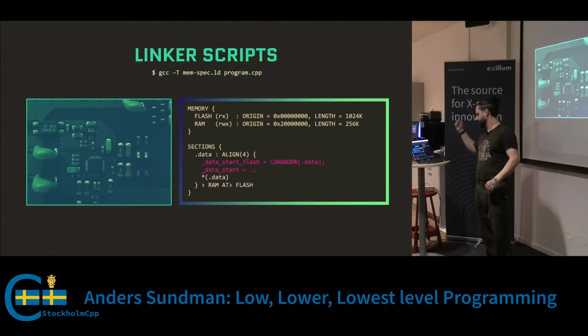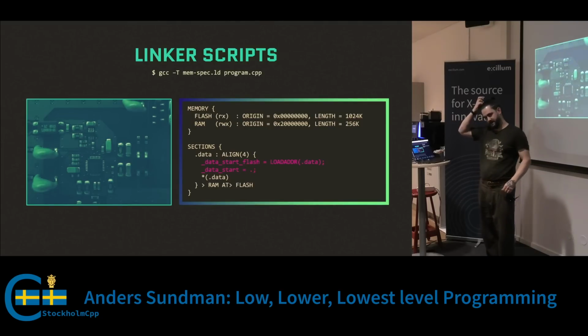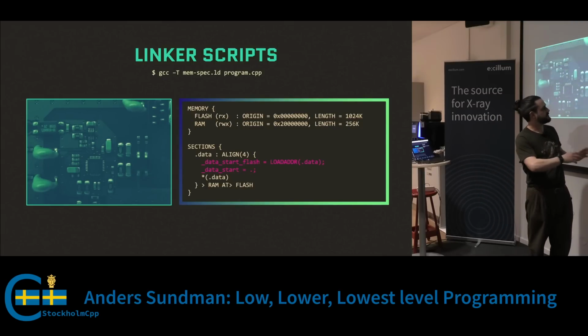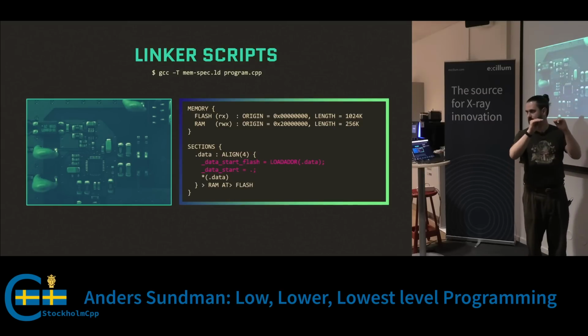Then we need to deal with the data. And the data was a little bit tricky. Remember, there's RAM and there's Flash. So the data values are in Flash. So we need actually two starting points here. We need the starting point in Flash, and we need a starting point in RAM.